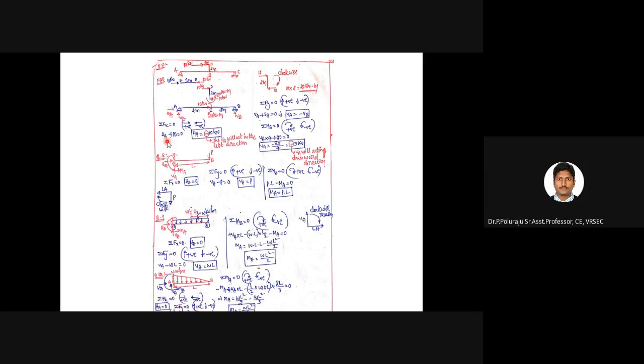But here when you are calculating HA plus 10 equals 0, you get HA equals minus 10. That means the HA will act in the left direction. Oppositely HA will be acting. And how to calculate this clockwise couple moment can be seen here, which you already placed with the red color. And after applying the summation of Fy, finally how to find out the VA. And VA is minus 5 kilonewtons, so VA will act in the downward direction. Okay, because it is a couple actually,